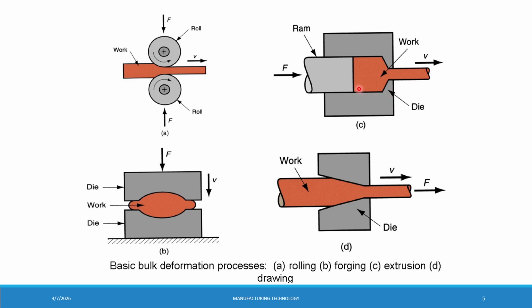So in this extrusion process, we initially put some raw materials into a cylinder-like structure, like how your injections are, and then you apply force on that material. The material is squeezed out of an opening, and the shape of the opening creates the type of structure which is created. If you have a round opening, a round bar-like object will come out. If it has a square hole, then a square bar will come out. This process is utilized for creation of your bars, your pipes, your tubes, and structures like that.